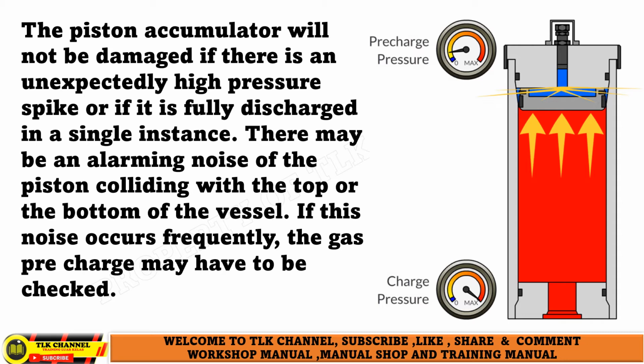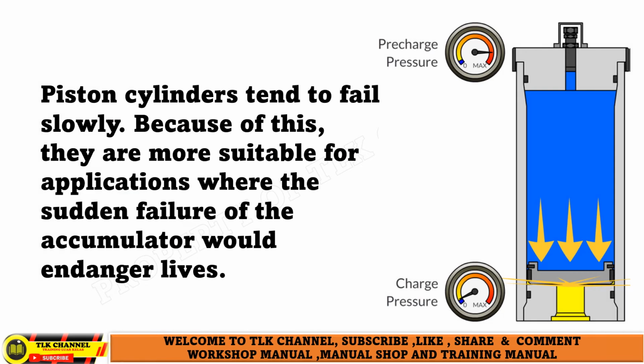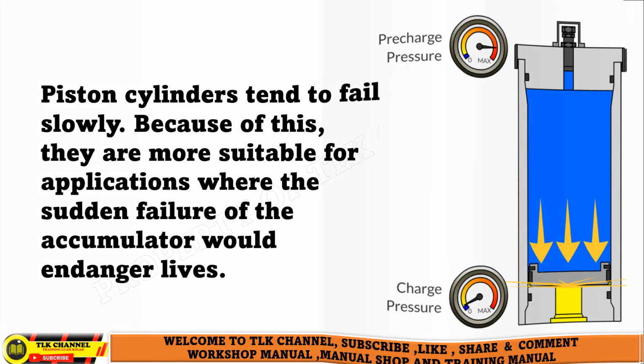There may be an alarming noise of the piston colliding with the top or the bottom of the vessel. If this noise occurs frequently, the gas pre-charge may have to be checked. Piston cylinders tend to fail slowly. Because of this, they are more suitable for applications where the sudden failure of the accumulator would endanger lives.